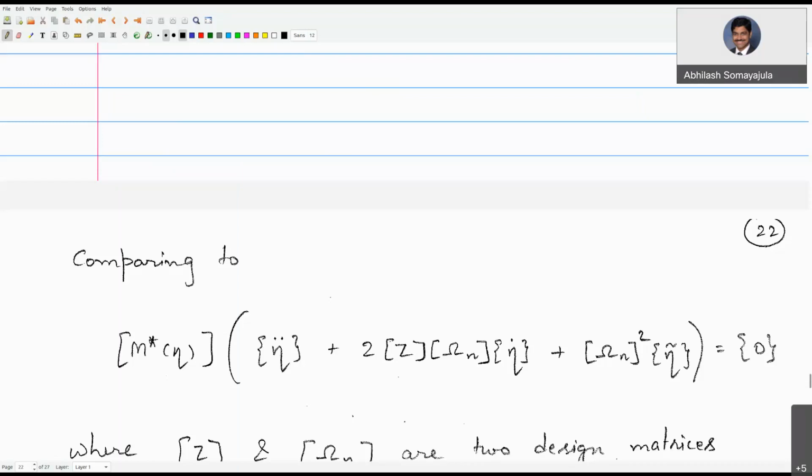And also the other aspect is that most of the ships which we look at are straight line stable, which means that without any open loop control, the system is stable. Right? In the sense that if I give a certain amount of rudder, I usually get to see a certain amount of turn rate. But that may not be true for aircraft. Without a feedback control, they may be very unstable. It may not be flyable without a control system in place. They are designed so that they can be highly maneuverable.